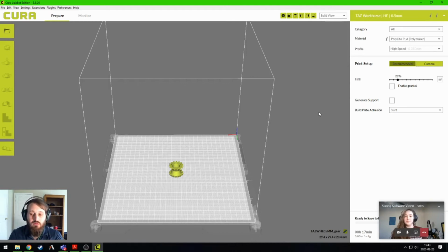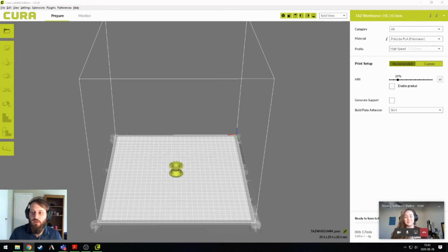Could we find out? Yeah, absolutely. If we Google, yes, we could definitely find out if we need that specifically. Do you have any background? Because you always default to what is yours? You said it was a grid. So I usually do grid if I'm doing something large. However, I'll do a thicker shell, which I think we'll talk about a little bit later. I'll do a thicker shell with basically less infill with the grid pattern, and for the most part, when I'm printing my miniatures, it's just 100% infill.